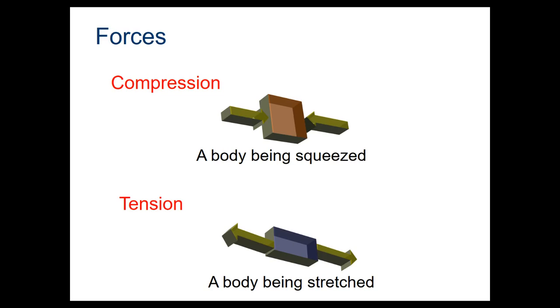This is more of a traditional truss bridge where you have steel beams that are connected together at corner points, and those vertices where they join together will be clamped together multiple different ways. A lot of them are going to be put together with gusset plates where they've got either a rivet or a giant bolt that's going to hold those things together.